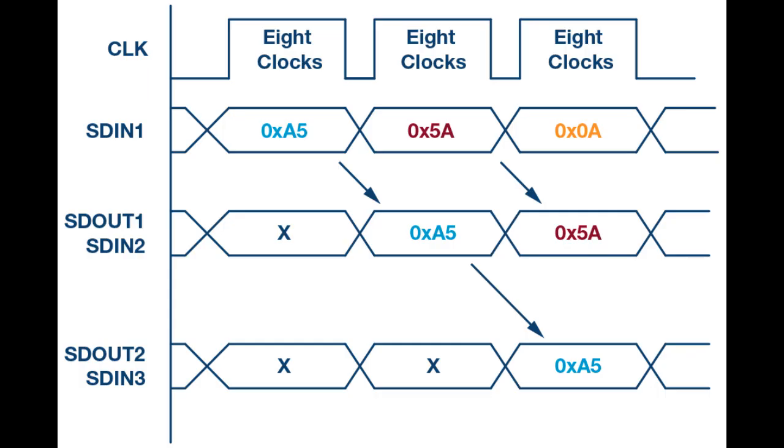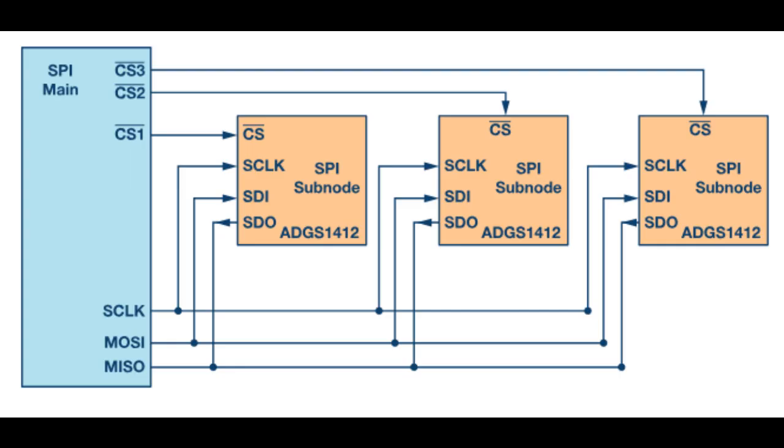Let's discuss the slave. The master can choose which slave it wants to talk to by setting the slave's CS/SS line to a low voltage level. In the idle, non-transmitting state, the slave select line is kept at a high voltage level. Multiple CS/SS pins may be available on the master, which allows for multiple slaves to be wired in parallel. If only one CS/SS pin is present, multiple slaves can be wired to the master by daisy chaining.